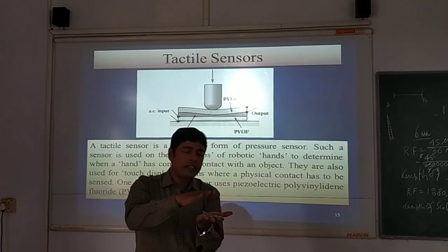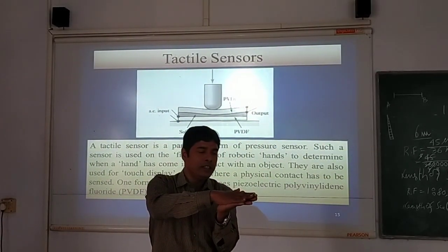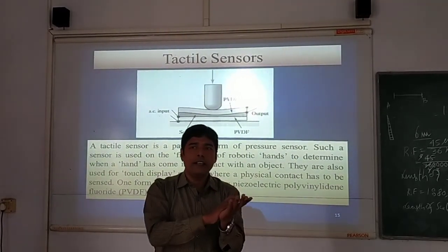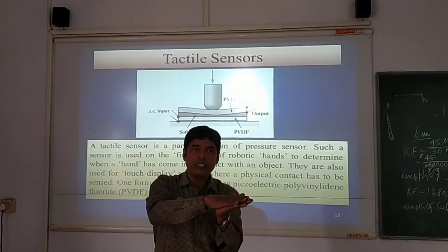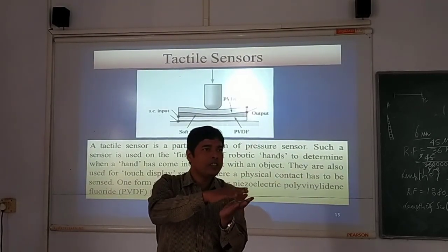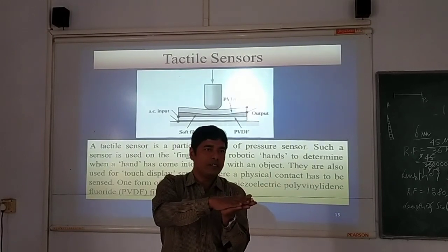When a material having the property of reverse piezoelectricity has an alternating current applied, its surfaces will be subjected to periodic changes of opposite charges, and it will elongate and compress periodically. That is, vibration will occur.